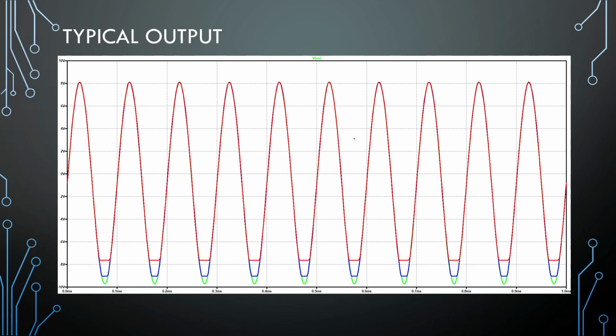Now, most of our amplifiers, even op amps, can't drive very small loads, and that is why we need power amplifiers. Right, so the voltage in must be equal to the voltage out, but with some oomph to drive a load of some sort. Okay, so for the Class A, the typical kind of output that you can get is at the top of the waveform. You will rarely have any issues unless you reach the top rail.